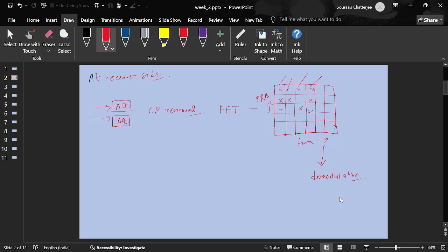So I need an LDPC decoder for each possible modulation scheme, right? Based on my SNR, whatever I as a receiver am feeding back to the base station, it can transmit anything from 4 QAM to 256 QAM in the 5G framework. So if I plan to directly operate on symbols, I would need LDPC decoders for all these separate modulation schemes, and that's not really a viable option.